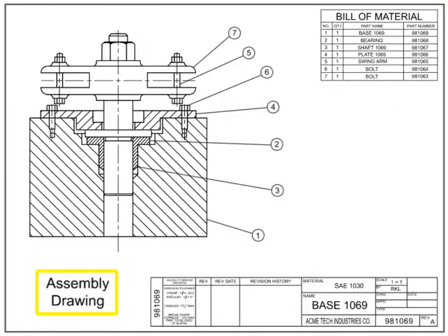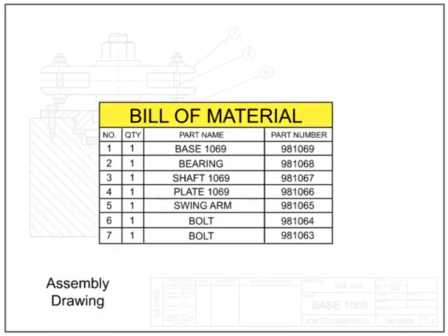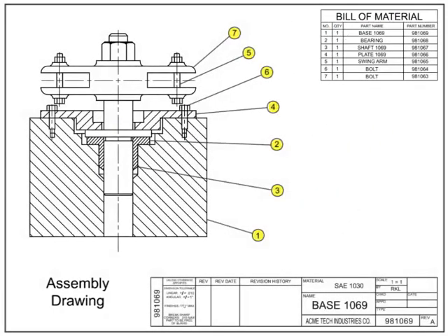An assembly drawing shows two or more separable parts joined to form a final product. The bill of material for an assembly drawing lists all the parts required to make up the assembly. Each part is given an item number, which is then referenced in the field of the drawing with a balloon for ease of location. Older drawings sometimes list the zone location in lieu of a balloon.